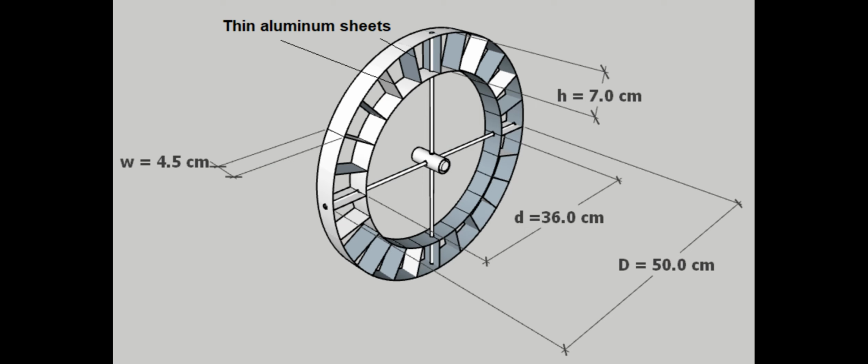The first flow straightener sometimes is called an empty chamber because it does not contain anything except a number of flow straighteners, which are just very thin sheets of a metal, usually aluminum, with a thickness no more than 0.5 millimeters. Their purpose is just to split the airflow passage in a multiplicity of passages to linearize somehow the airflow coming out from the fan.